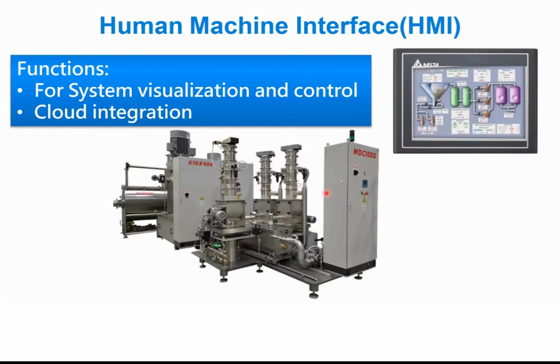In the industrial automation, one of the most used visualization system is HMI, human machine interface. There's also another one called SCADA. The difference between SCADA and HMI is quite simple. HMI is mostly local based. It means that on most machines, you install the HMI directly on the machine or very close to the machine.